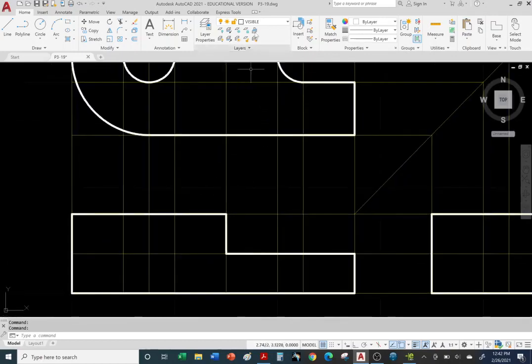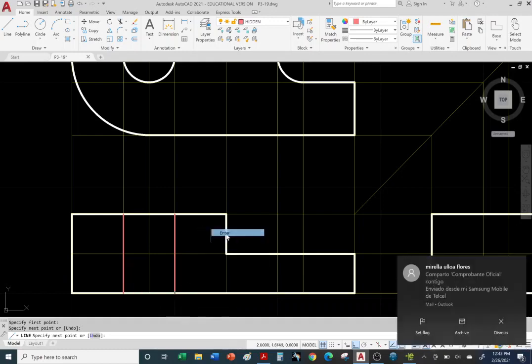All right, so let's draw our red hidden lines. Let's go to the hidden layer. Okay, line command. And again, from the left quadrant of the hole in the top view, we can come straight down and draw our hidden line. Let me turn on ortho. Okay, hit escape to exit. I'm going to use the same command again, so I'll just hit spacebar. And from the right quadrant of the hole, come straight down. Okay, there it is. Right click, enter.